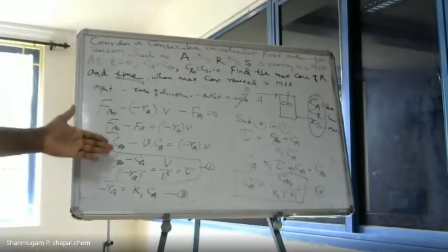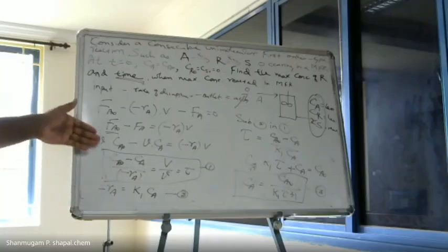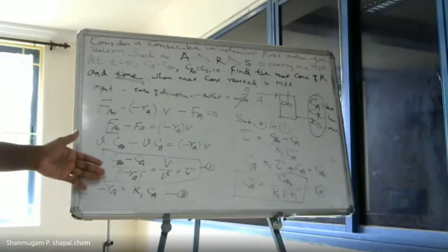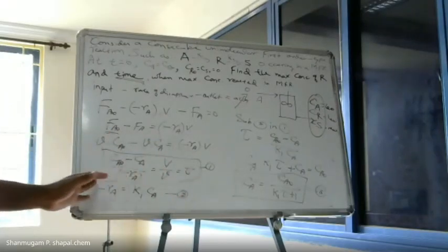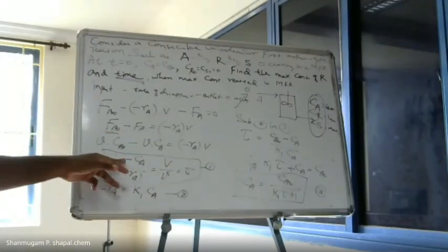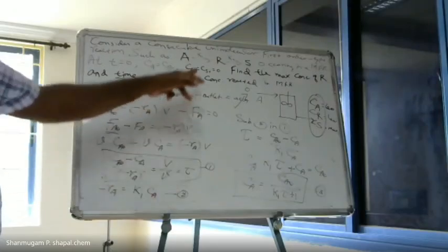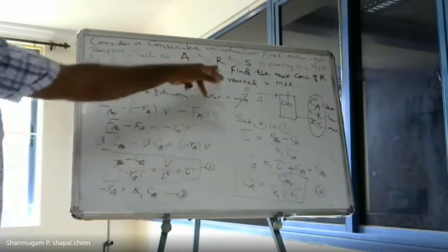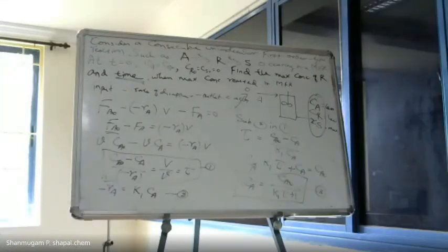So you can even directly start from the performance equation. I just derived the performance equation here, and from this, tau equal to CA naught minus CA by minus RA. So minus RA can be K1 CA. So we consider this is a first order.